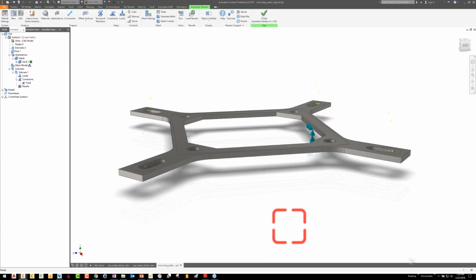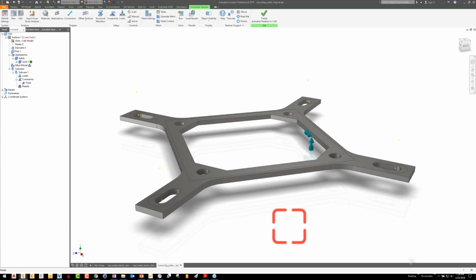My loads are going to be 12 pounds on each one of those thumb screws, kind of the maximum we intend to design for. So I want to see what kind of stresses develop in this plate under that kind of loading, and eventually the entire assembly under that loading. So the screws are no longer here.